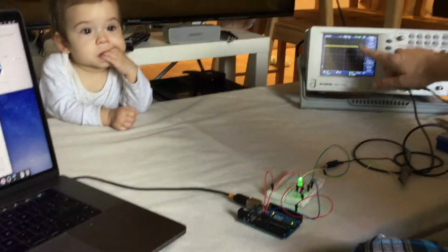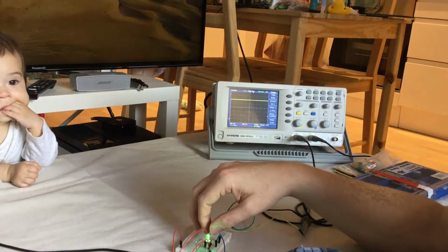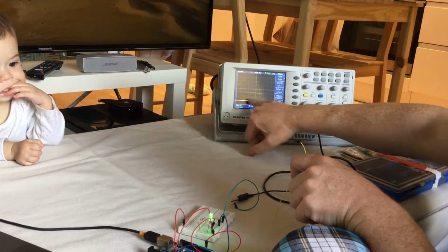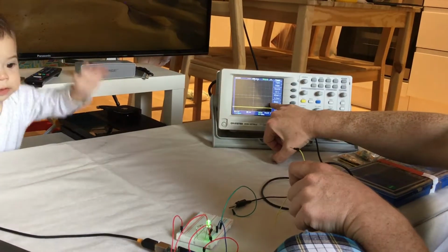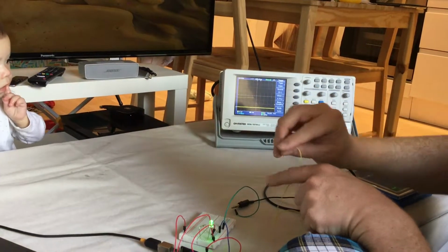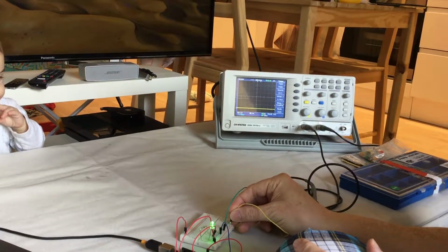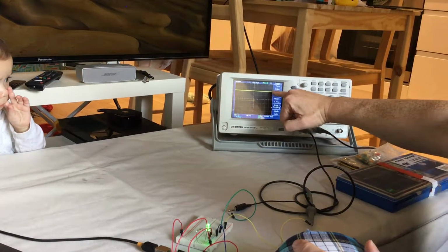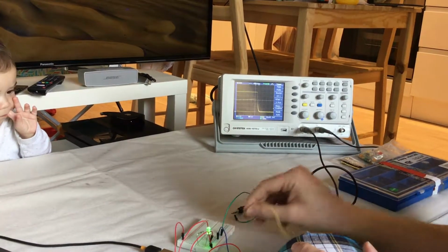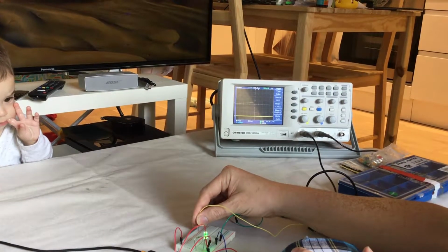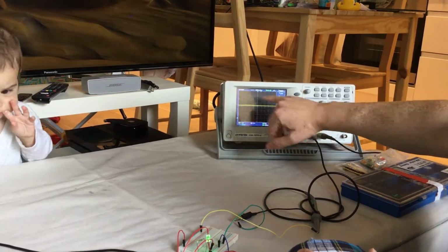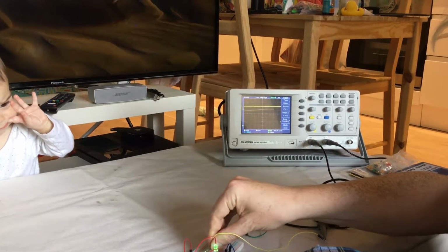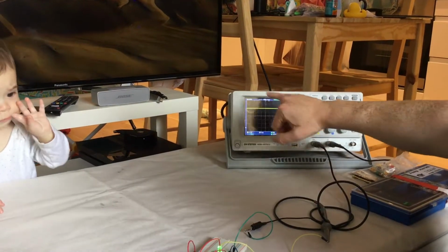And in the background, if you look here at the oscilloscope, this is the probe wire here. This oscilloscope is currently running from 0 volts. These are each 1 volt divisions. If I put the probe against the 5 volt line, we can see that it jumps up 5 divisions. If I put it against the 3.3 volt line, it jumps up about 3.5 divisions. There's ground. And this is the LED pin, which is currently running at 5 volts.